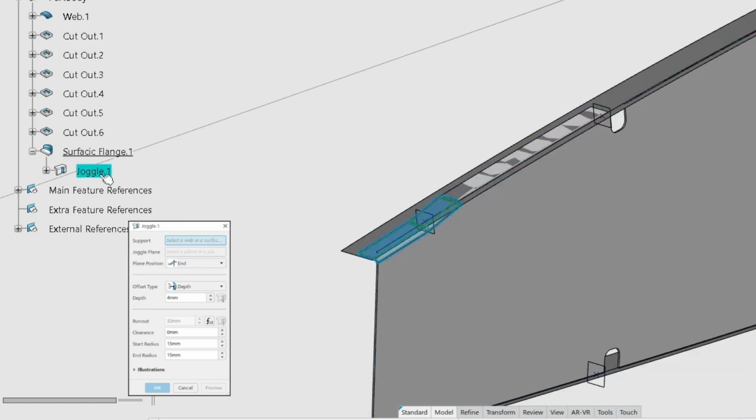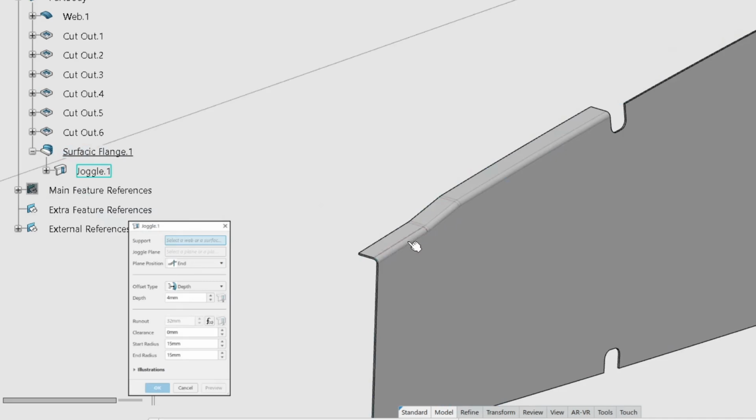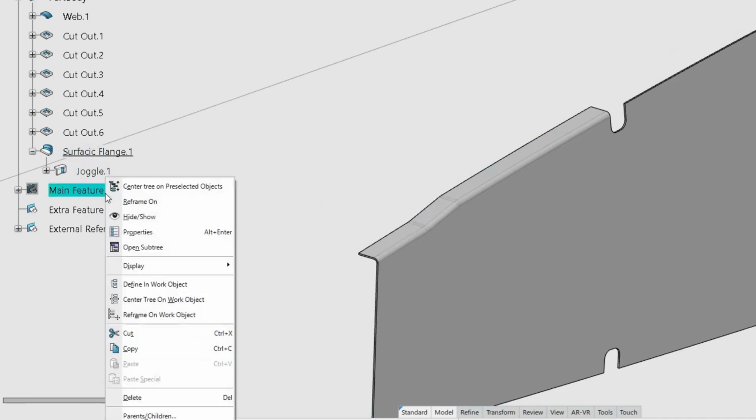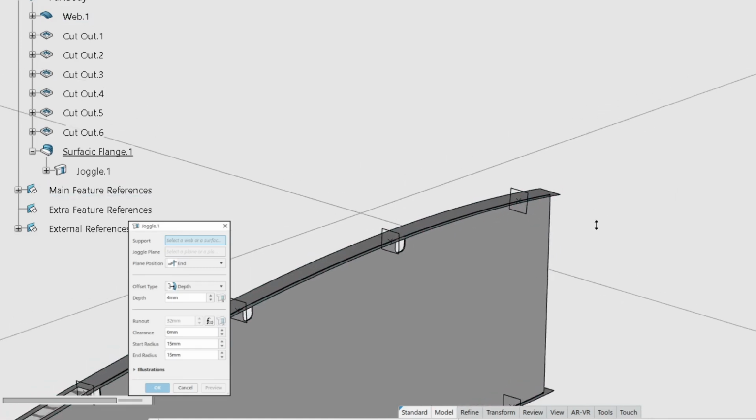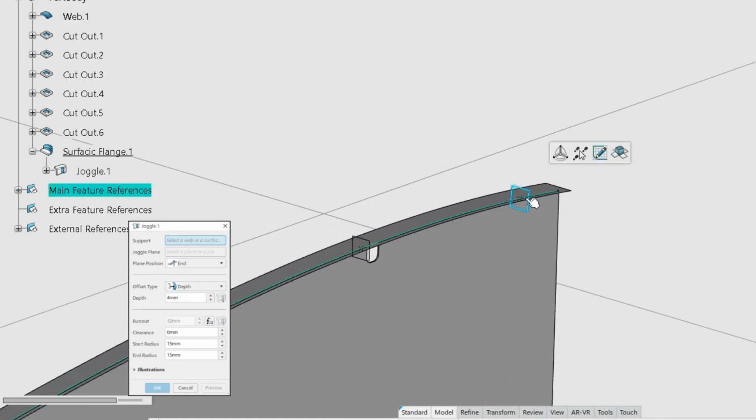As you can see, the flange has been pressed in to allow the rib to fit in the spar. If your first flange was created at the front of the rib, then do the same procedure using the corresponding plane, as the outcome will be the same just on the opposite side.